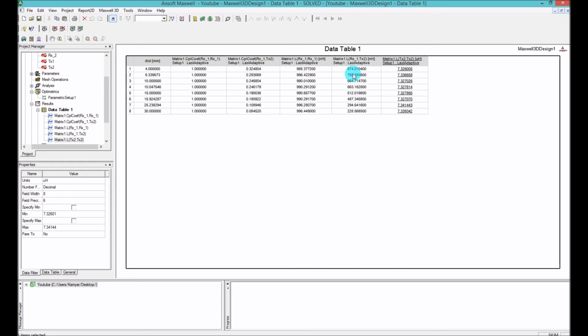It's pretty small. So what I'm going to do is put some values for the capacitors, CR and CT, in a way that these two are resonating exactly at, let's say, 100 kilohertz, which is the same as WPC. Let me find the value for the capacitor.